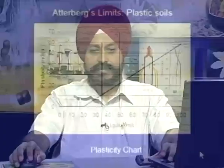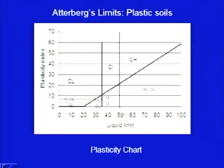cohesionless soils. For cohesive soils we have to conduct the Atterberg limit tests, liquid limit and plastic limit. Here on the x axis this is the liquid limit, on the y axis it is the plasticity index. Plasticity index means liquid limit minus plastic limit, and then on this chart we plot the position of the point. Suppose the point is somewhere here, then it will be clay with low plasticity. The limits of different clays for different classifications are like this.